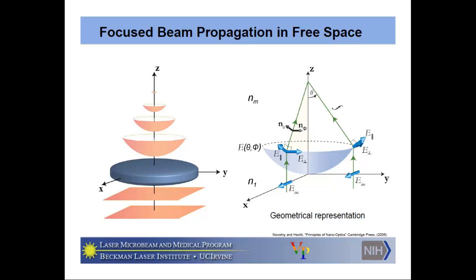and when it comes to this location, we consider parallel and perpendicular components, and for these components we have to calculate the projection of this incident vector. Now in this case, E perpendicular, which is 90 degrees perpendicular to E incident, is going to be 0, and E parallel is going to be E incident. And at this location, E parallel is going to be 0 because it is along the y-axis, and E perpendicular is going to be negative E incident because it is directed in the other direction, towards the board.